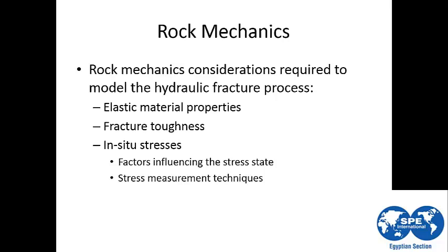Both of them control your geometry and how this frac is going to propagate inside the reservoir. From the rock mechanics point of view, we have elastic material properties, related to Young's modulus and Poisson ratio, the fracture toughness, and the in-situ stress.